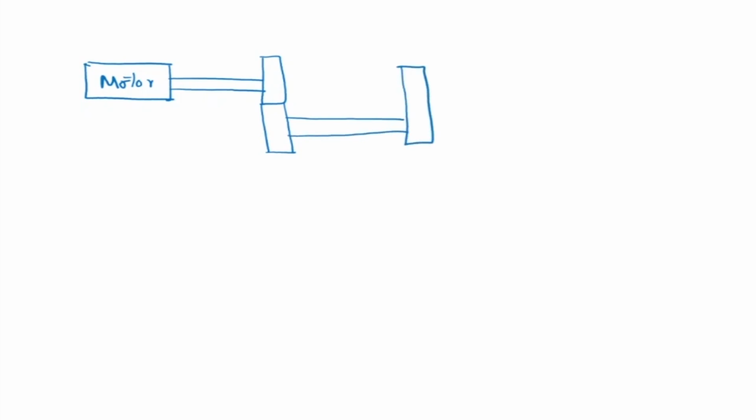Basically we have a motor, then we have bearings to support the shaft of the motor inside. Then we have gears with a gear ratio of N, and there are bearings on the other side also. Now let us write the various terms that we are going to examine. The motor produces the torque tau m, and the rotation angle is theta m. At the bearing there is friction, which is Fm, and the inertia of the motor is Jm, on the motor side.